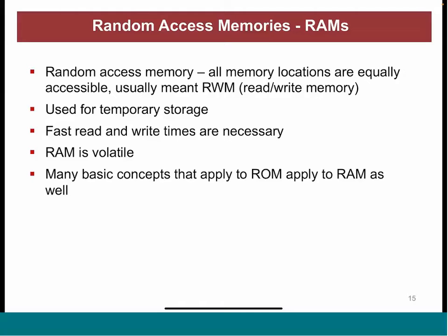Flash memory is like a hard drive. When you save the code there, it stays there, even if you power off the device. And then once we power on the device, the code goes from the flash memory to the RAM, and then the microcontroller starts the execution, because it will not stay in the RAM when you disconnect your embedded system.